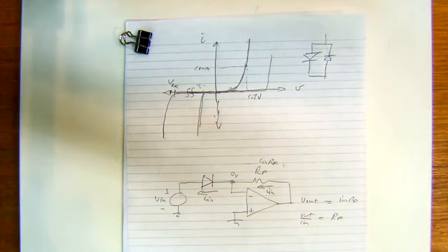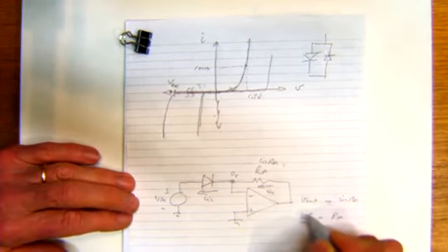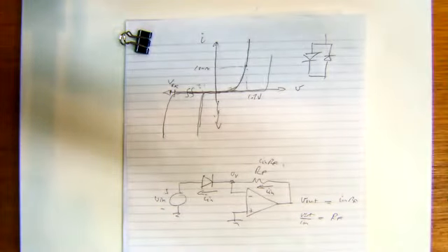That's the signal current through the diode. Now, there can also be some what we call bias current, some DC current that flows. Notice that these symbols here are lowercase symbols, so they're to do with the small signal part.